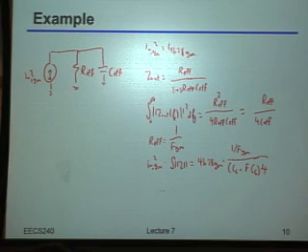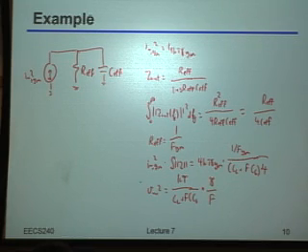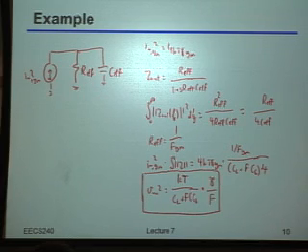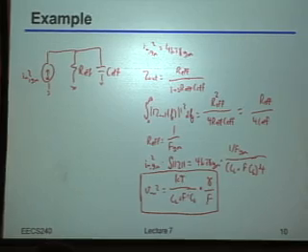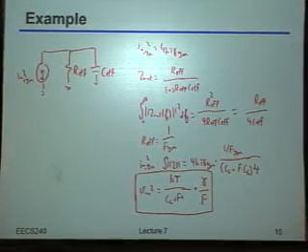So you're just going to end up with the total noise at the output equal to kT over CL plus F times CS, times gamma over F. Okay? Oh, I'm sorry, there we go. F times CS.